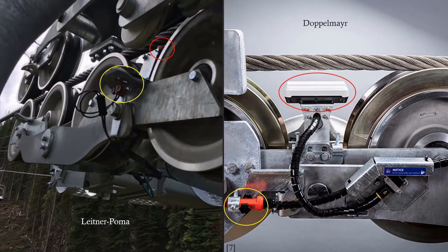An important component of line gear is the rope monitoring equipment. This is used to quickly alert operators and maintenance personnel if there is a situation that could cause a derailment. A lift that moves fast enough has to have a primary monitoring system and a backup monitoring system. The primary monitoring system for Leitner Palma and Doppelmayr lifts is shown circled in red. Here, proximity sensors are used to detect where the haul rope position is exactly and stop the lift automatically if it is outside of this position.